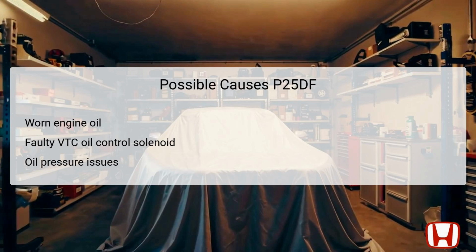Additionally, issues with engine oil pressure can also trigger this DTC. Low oil pressure can arise from various sources, including a failing oil pump or clogged oil passages. Identifying the specific cause requires careful inspection of these elements.